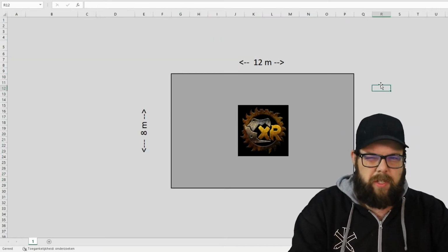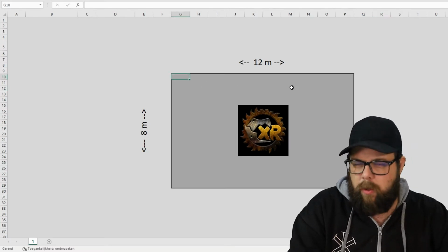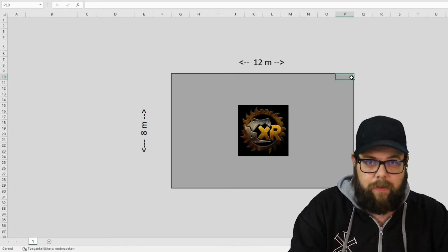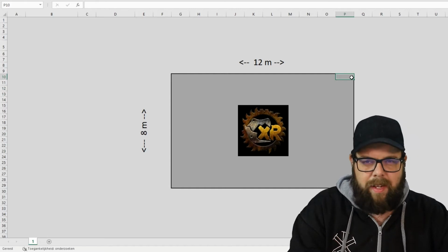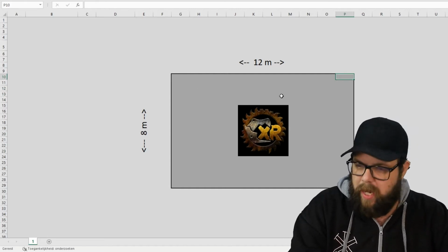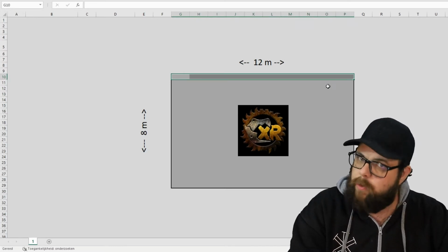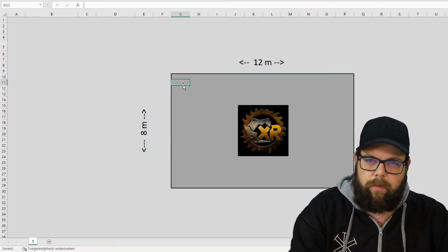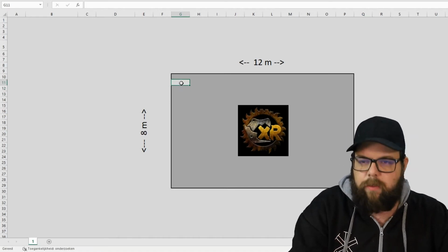So what's a fast robot? Now, if you remember the Hypershock fight, Hypershock went from one side to the other side in less than a second. And this was the BattleBots arena, which is a little bit bigger. But let's focus on the arena in the UK. So 12 meters. If you cross the whole arena in 1 second, you have a really fast robot. If you cross it in 2 seconds, it's about average. If it's important to have a well-controlled robot, maybe 3 seconds, from one side of the arena to the other side.